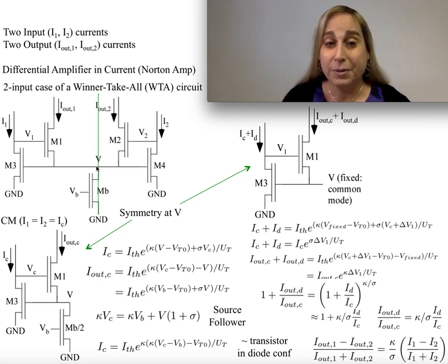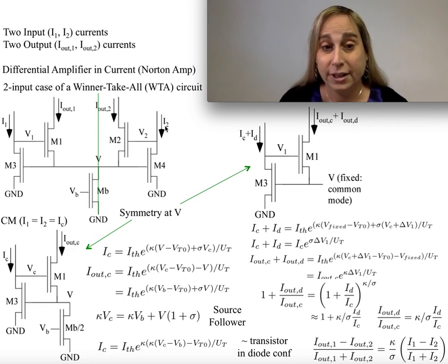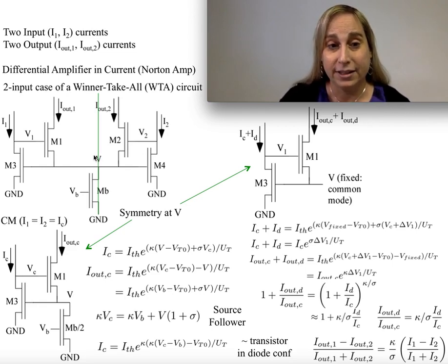That being said, I'm going to keep this in a large signal, device level structure, so you can see all of the larger structure. There are ways to deal with common mode and differential mode in these cases. The first thing is the common mode case, which is easier to understand even in large signal, because assuming I1 and I2 are identical and everything else is matching, this half of the circuit will basically look like this half along the axis of symmetry.